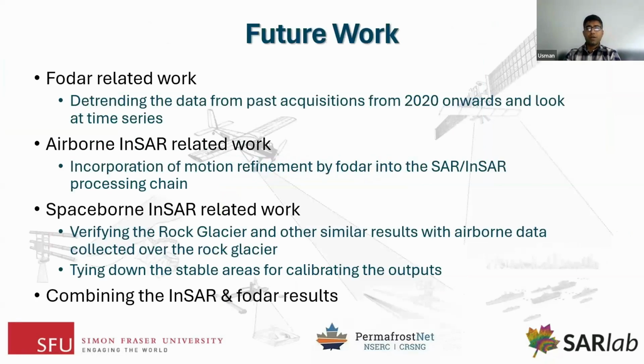In future, I'm targeting to improve the FODAR work by detrending the data from the past acquisitions, as I showed you that there were trends in range and azimuth, or in north and south, and there were biases, so we could detrend it and see if we can still make out some kind of time series analysis from the FODAR data. And for the airborne, we are still in the process of incorporating the motion refinement that we extracted from the FODAR sensor and incorporate that into the InSAR chain and see if that improves the results further.